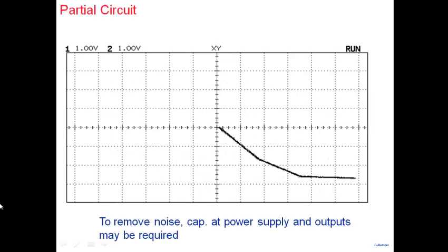This is the complete circuit for one half. Actually, we were required to generate this in the first quadrant, and in this case what we have is in the fourth quadrant. But note that all we have to do is add an inverter and invert this, and we'll get this in the other half. So that's trivial. You can clearly see all the segments here: the first segment with the slope of 1, then a slope of 0.5, and then something which is flat.